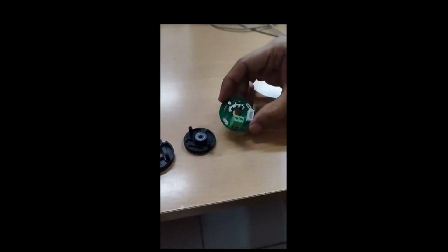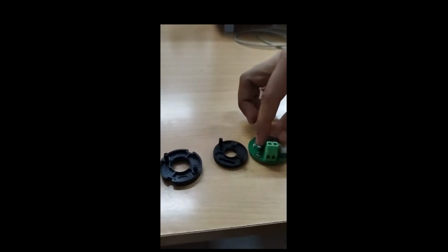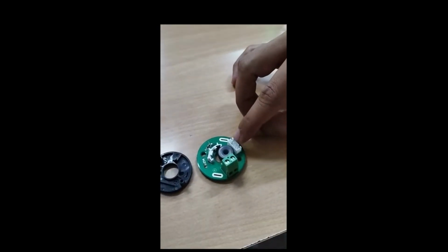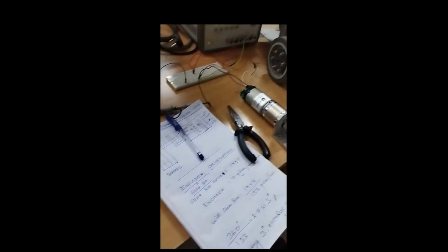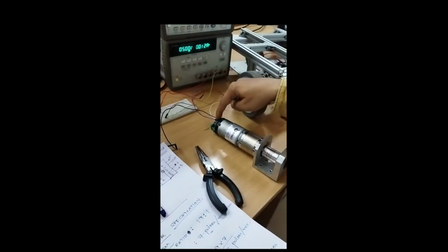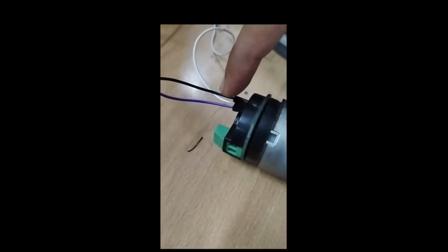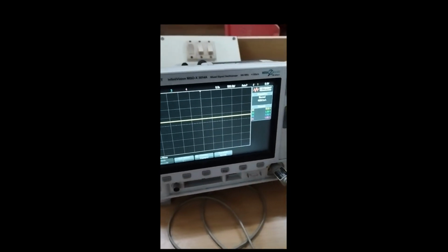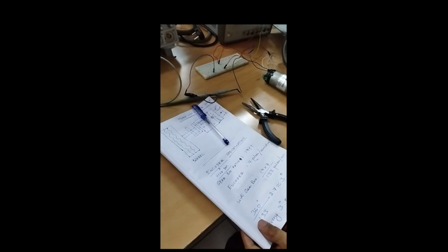And the encoder part, what you see on this laptop, has 2 Hall effect sensors, and we have a magnet here. This magnet, with the small circuits, will produce 7 pulses per revolution. So this is connected together, as you see here. There is a VCC and ground, and the pulses are taken out, and then we are able to see them on an oscilloscope, something like this. Before going to the output waveform, we are going to discuss the theoretical part of it.